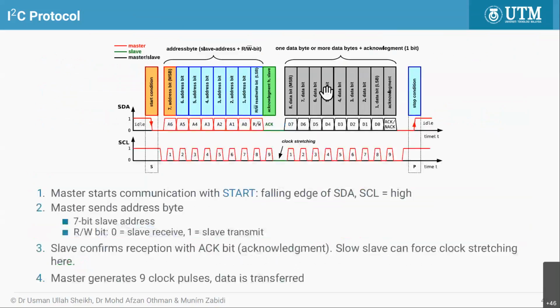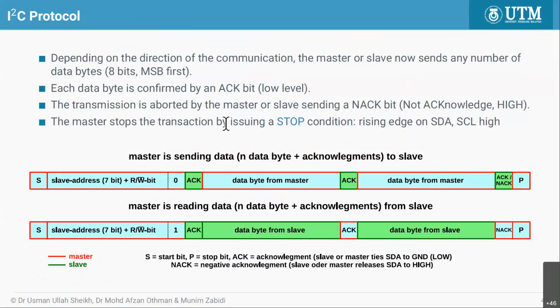Okay, so here it is possible for the address to appear only once, but the data can have multiple sets. You don't have to give a separate address for every data. Then the transmission can be aborted using the NACK bit, or not acknowledged, and there is abortion.